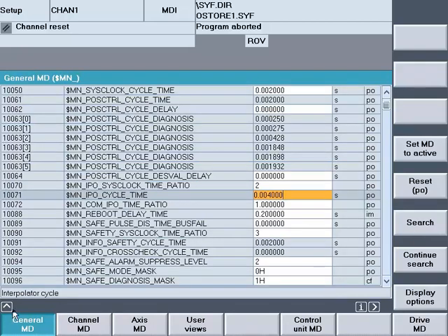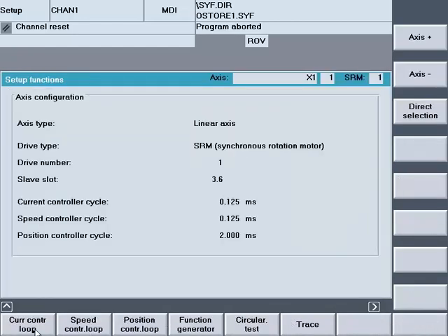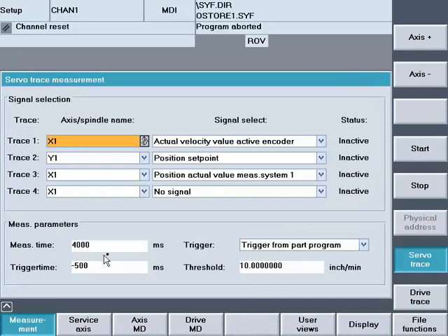So my maximum trace value that I can do and get good resolution is 2,047 times 4 milliseconds. It's not going in under decimal here, bummer. But it's going to be a little bit over 8 seconds, about 8,200 milliseconds, give or take. So what this will do is let me run a trace. So I will, and it runs. I get 8 seconds worth of data.